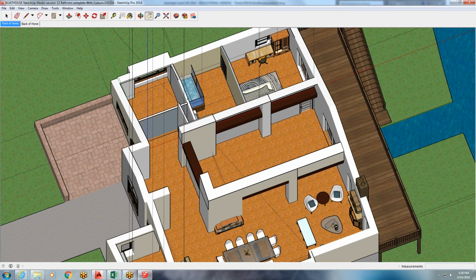But if you're ever building a model, I think that's one, as I think back on projects that I've seen from students and even from my own work when I was in intro, that gets easily overlooked: the closet. The reality for home buyers is if a room doesn't have a closet, it can't be considered a bedroom. It has to have a 24-inch deep closet in it to be considered a bedroom. So otherwise, you can't exactly claim it to be one.